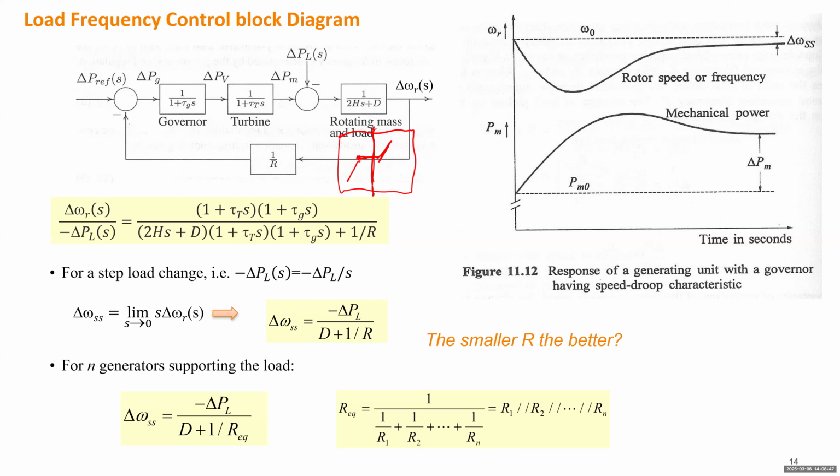Yeah, the control design. Maybe to answer that question, I would say there can be both a physical dead band, depending on what governor and turbine you have, or there can be an intentional dead band. Yeah, it can be both. Some design of the dead band may be made by the generator manufacturer. Your generator is very expensive equipment that needs to be protected, which means you definitely don't want to make it too responsive and give more risk of damage. And actually, it doesn't have to.